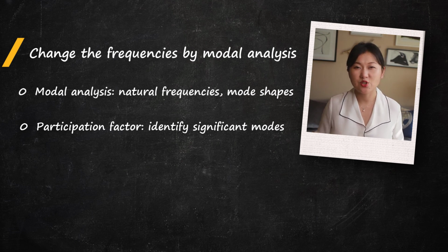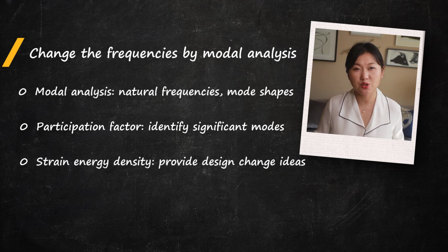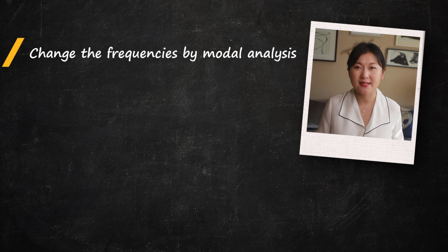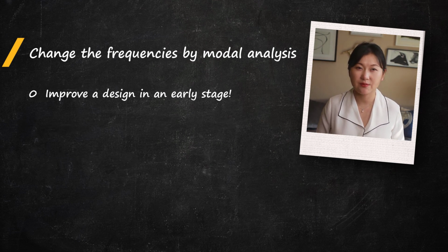And finally, the strain energy density output helps to provide insight regarding the structural behavior in design. That is, where to add materials to increase the stiffness or where to remove materials to reduce the mass. Thus, the modal analysis results, though being relative, give us information regarding the dynamic response of the system well before we perform more computationally expensive dynamic simulations. The modal analysis can be used as a quick way to improve the design at the early stage.